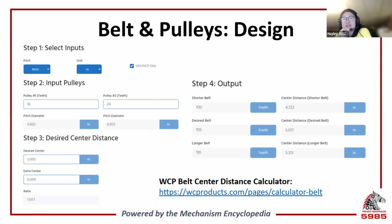And then step 3, you put in the desired center, which is how far apart you want the two things that you're transmitting power between to be. Then the calculator will spit out 3 different belt options with the center distance closest to what you want. Usually you can just take that middle one, but the other 2 also show you the other options that you can use.